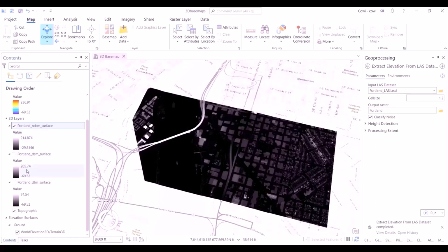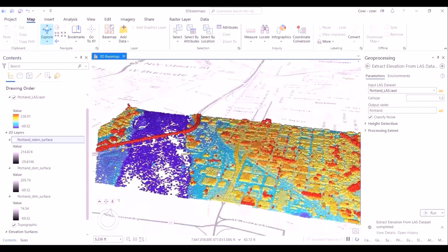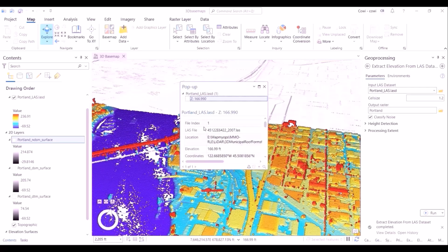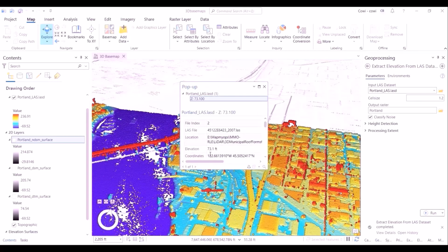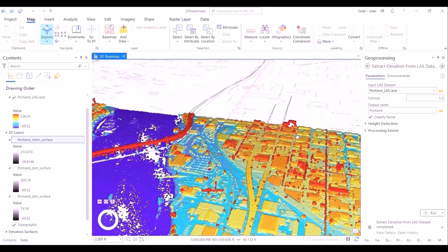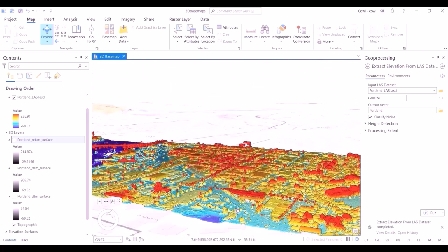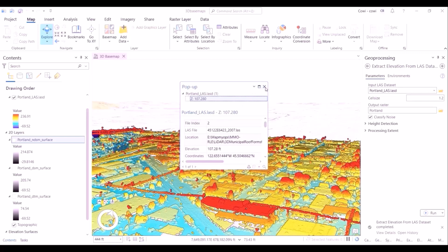Let's switch on the LiDAR point cloud layer once again. We'll do some corrective actions now, because you see that the bottommost point is at the height of minus 70 feet. So obviously there is certain discrepancy or error in the LiDAR calculations. Even the topmost point, just verify by clicking on the various features in the dataset to understand whether it is a true representation or not.